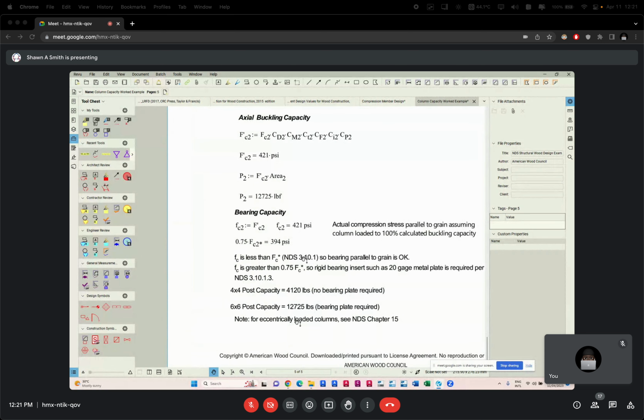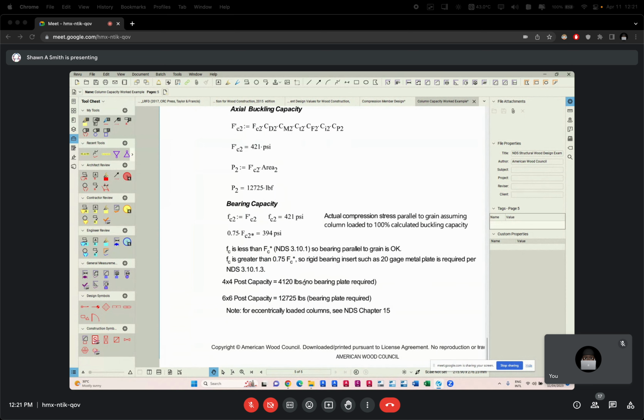If you were to look at it from a bearing perspective, they are saying that you would need bearing capacity for the larger one. Bearing plate, really. But we are not interested in this bearing plate thing. Like I said, we are not privy. No hardware in Jamaica is going to sell that. It's really one of the drawbacks why we're not so much into timber construction and timber design, because we do not have all the necessary accessories. We don't have the joist hangers, the connection plates, and all them things.